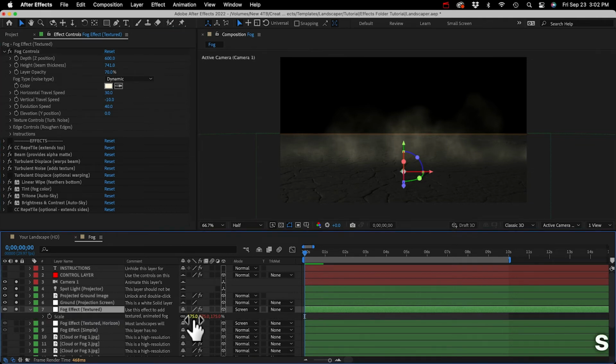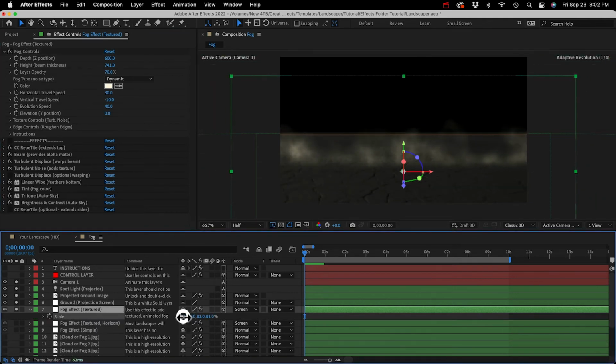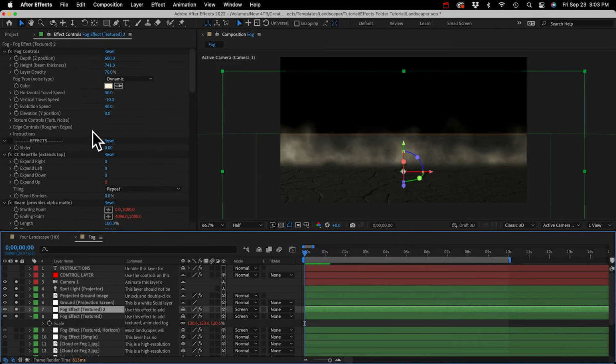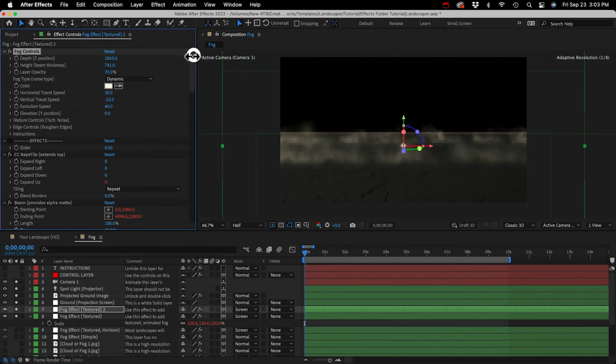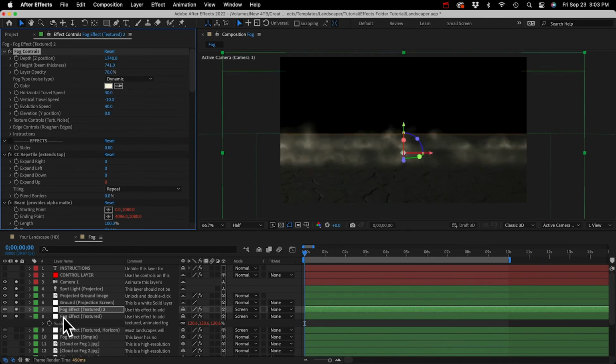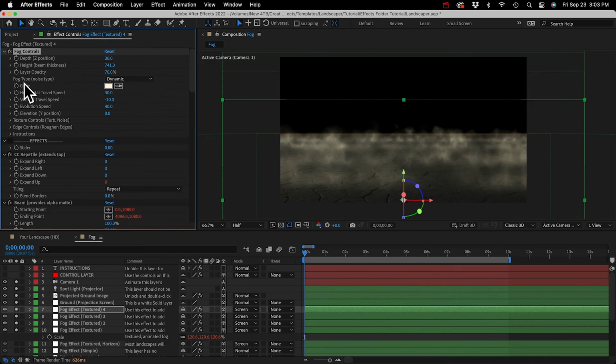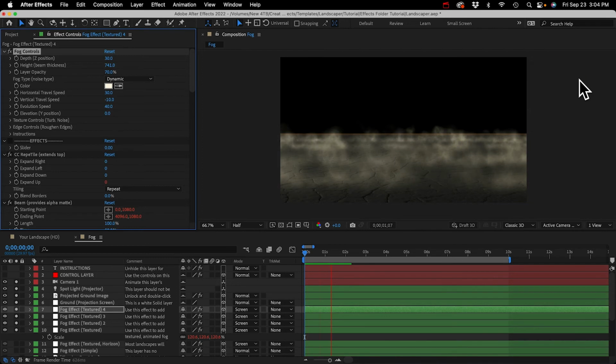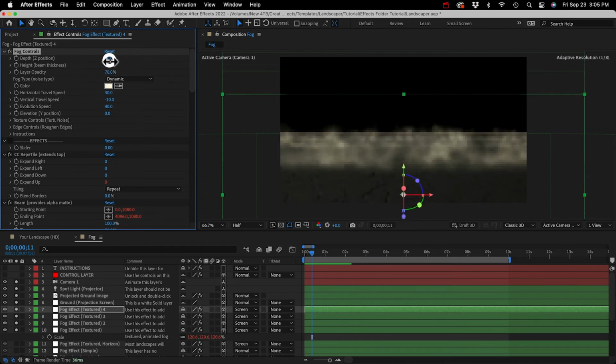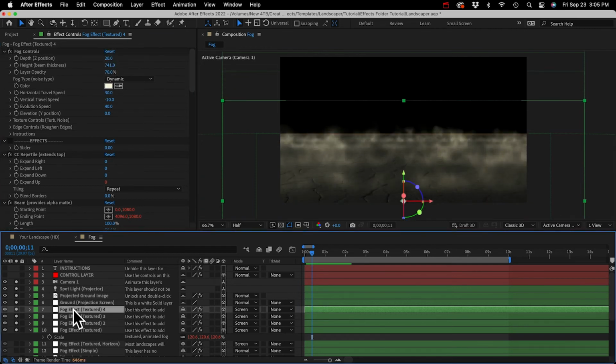So if you want to scale the layer so that it's a little bigger than your frame, like this, now you can duplicate this layer to make a few different copies and then push back each one a different distance from the camera. And the fog will look smaller, but you don't have to scale the layer up. It stays that same width. Just be sure to use this control when you move your fog back or forward. You can't do it with the position control down here.